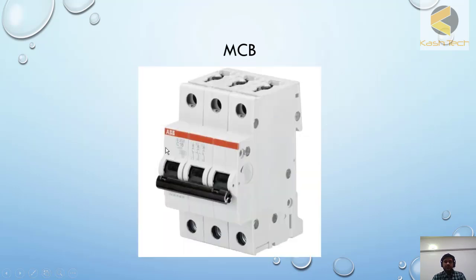This is the shape of an MCB in brief. This is basically a 3-pole MCB, and it is from ABB and C16. 16 is the rating of the MCB, 16 ampere, and they have shown the symbol, so just go through it. It's very simple.